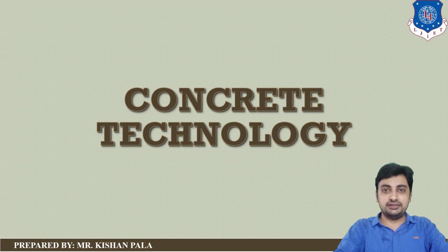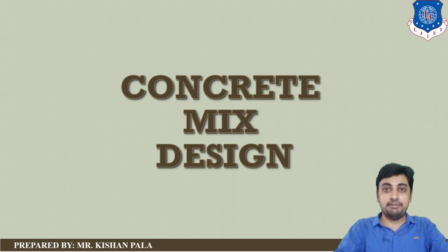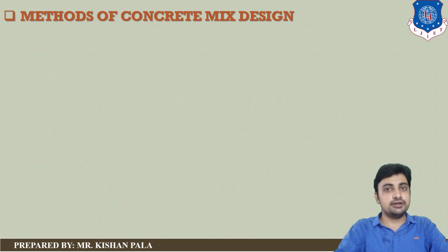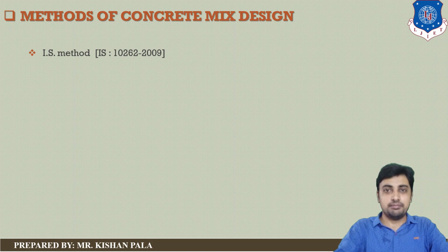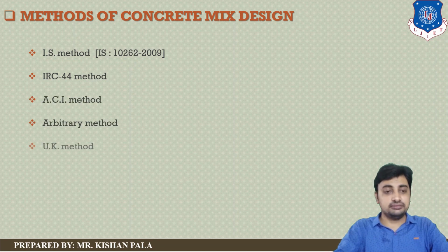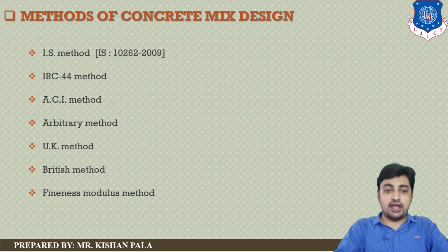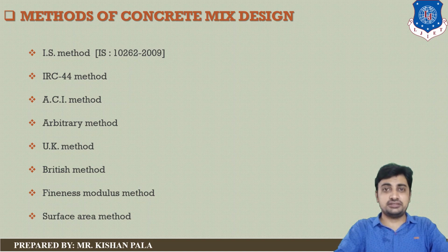Hello viewers, in this session we will discuss concrete mix design. As we know, we have different methods for concrete mix design like Indian Standard mix design. You can refer to IS 10262 2009, IRC 44 method, ACI method, arbitrary method, UK method, British method, fineness modulus method, surface area methods. You can choose any one for the concrete mix design.